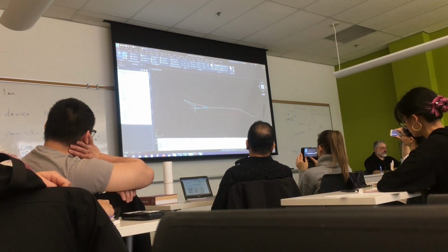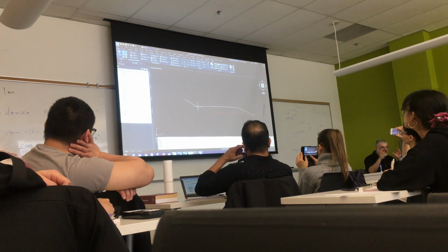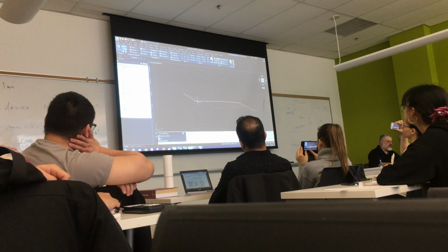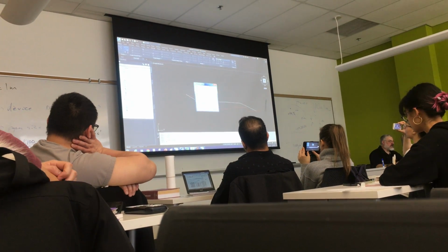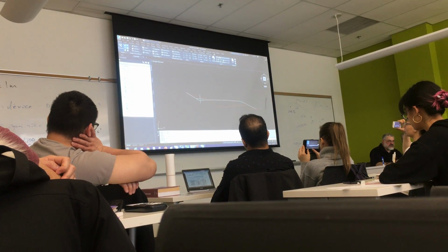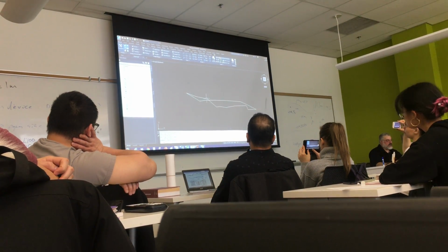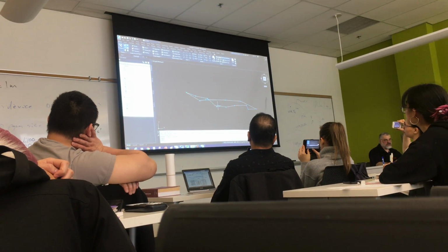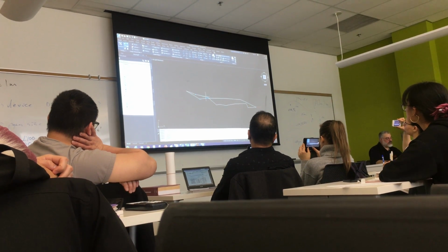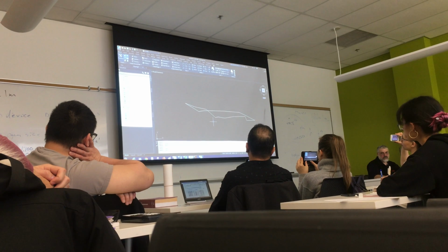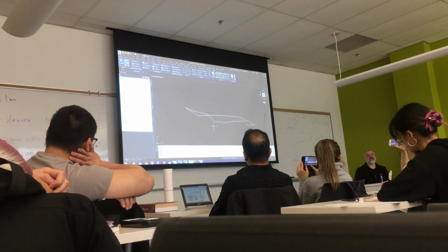Here's a better way. If your drafting is clean, if that's truly a closed figure, you can use a command called boundary, BO for boundary. You can pick a point, and if it's truly closed, it'll draw that polyline for you. And now you can list that, and it tells you the square meter end. This is total cut, this is total fill.